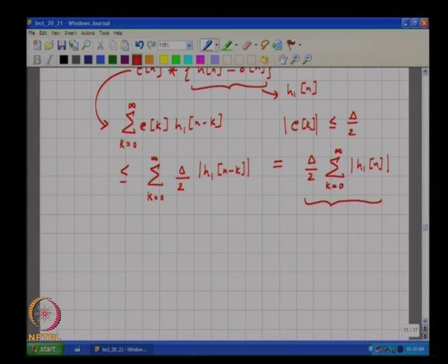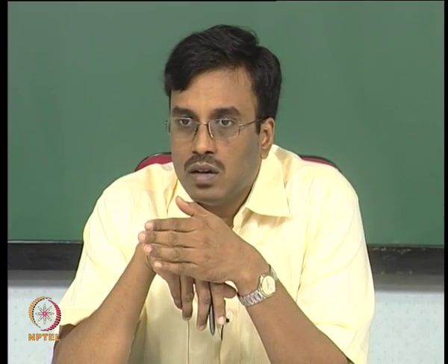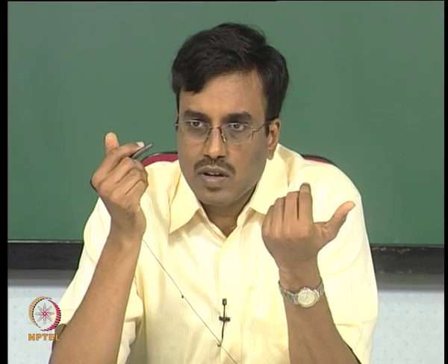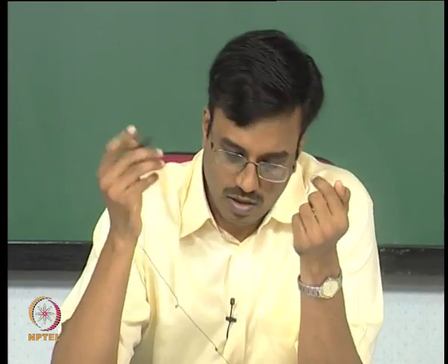And as we will go along, we will see how we came from the first order to the second order modulator can be repeated again, and you will get a third order modulator where the noise transfer function becomes 1 minus z inverse whole to the 3, correct, and you are expecting to do much better in band and worse out of band.